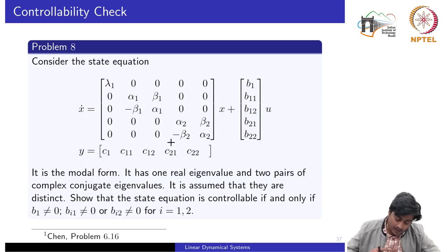So far, if we speak about the controllability checks of an LTI system, we had studied the rank test, the PBH test, and also characterizing the spaces by computing the gramian. Now this test is in terms of the Jordan form.